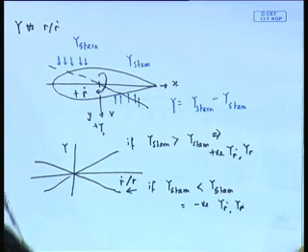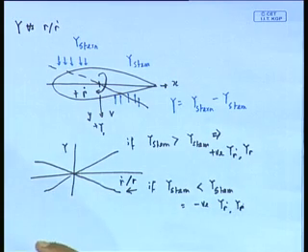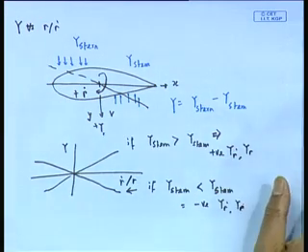Now the point therefore is that, as far as Y against R or R dot is concerned, that is another interesting thing. Y and R, this I will come afterwards. When it comes to Y and R or R dot, half the hull produces Y in one direction, other half of the hull, or half means aft part, in the other direction.